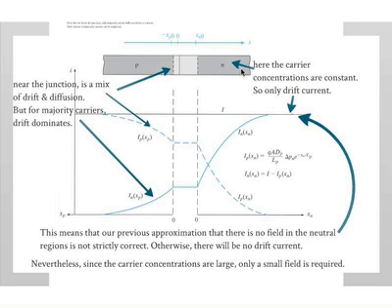But that raises an interesting problem. We assume that there is no field out here, remember? How can you have a drift current without field? Okay. So obviously our assumption that there is no field there is not quite right. That's another important point to keep in mind, that in order to have current out here, there cannot be diffusion current because there's no concentration gradient. It can only be drift. And for drift, you need to have a field. In order to have a field, you need to have a potential drop here. But our assumption is approximately correct because you only need a very small field, as long as this is heavily doped.